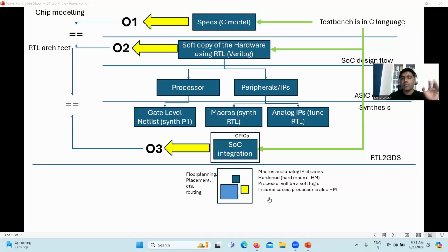Okay, so once we do this, this is a step where your front end, your RTL, is converted to gates, and these gates are properly placed and routed. You have all the AND gates, OR gates, flip flops, everything. There are no more if-then-else statements in this particular step. It is only metal layers. There are only standard cells.